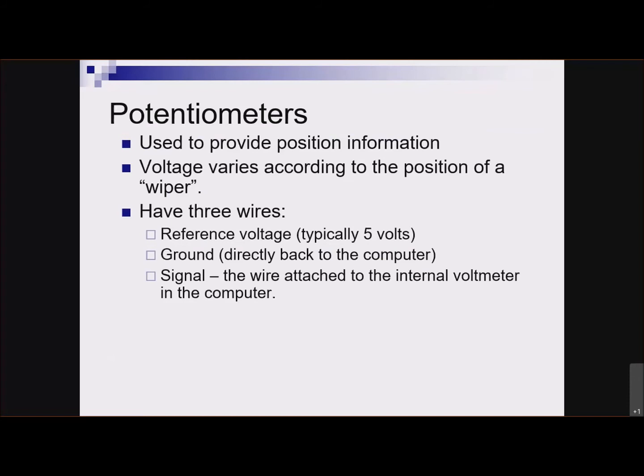So it's all over the place as you're going down the road, day, night, hot weather, cold weather. Is the air conditioning on? Are the headlights on? That battery voltage changes a lot. This 5 volts never changes. It's a voltage regulator inside the computer. So we have a nice, steady voltage level supplied to all of our sensors.